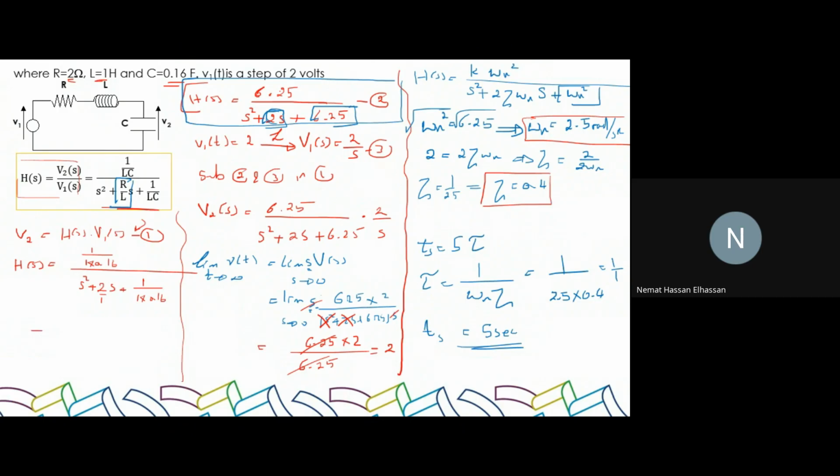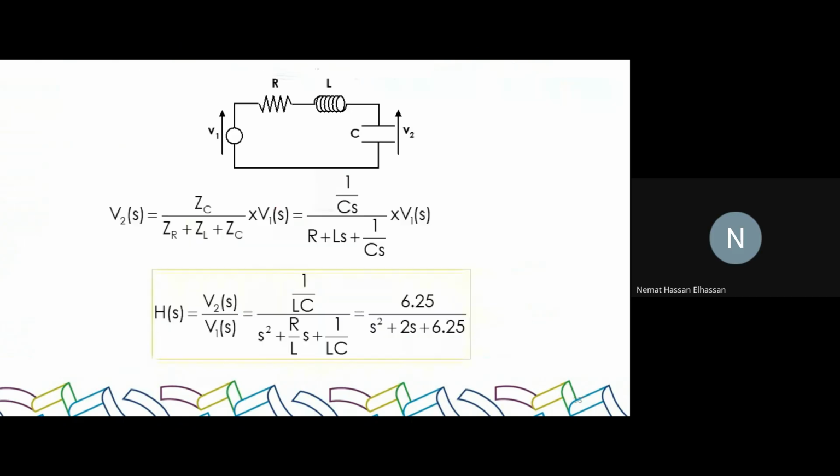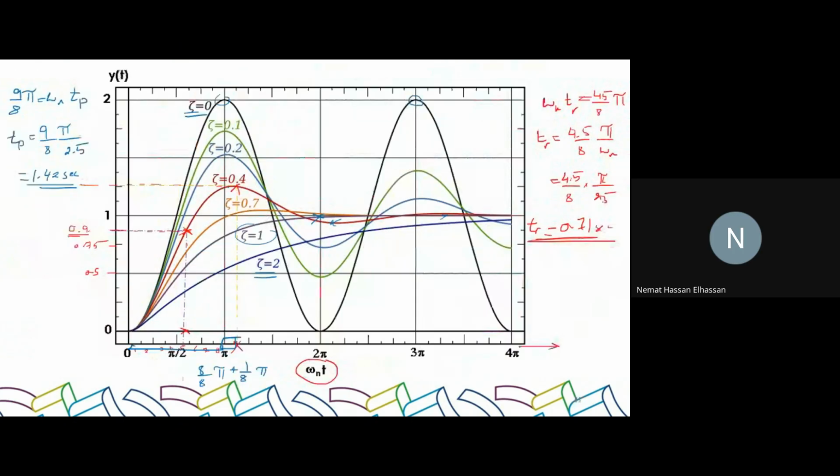So I will highlight this later, but you need to look at it from this perspective: how will it behave? Especially this delay is very important because it tells you how fast it is, how long it takes, or how accurate it is. Because if you look at this factor, it's not just time, it's frequency, right? So it also tells you how accurate you are in terms of frequency. We'll discuss roll-off later on, but up till this point, is it clear?